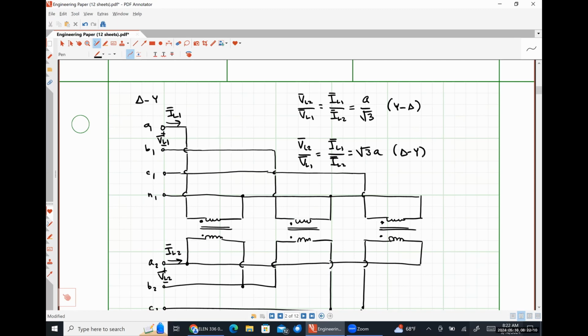It is no big old multimeter at all, right? A multimeter would not be rated to be able to do that safely. What we do is attach a transformer with a known turns ratio and use that to electrically isolate our measurement system from the live wires. Whatever we measure on the low voltage side of that transformer, we multiply that by the turns ratio, and it tells us what the voltage is on the lines.